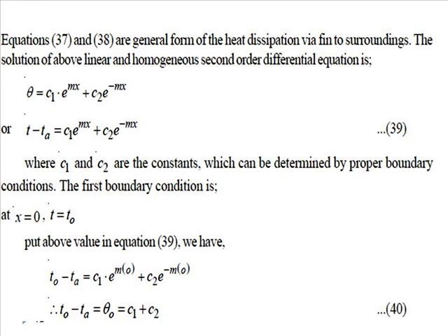solution of the above linear and homogeneous second order differential equation, which we learn in maths, is theta equals C1 e raised to mx plus C2 e raised to minus mx, where theta equals T minus Ta equals C1 e raised to mx plus C2 e raised to minus mx, where Ta is the ambient temperature, m is the fin constant, C1 and C2 are constants, and their values are available by